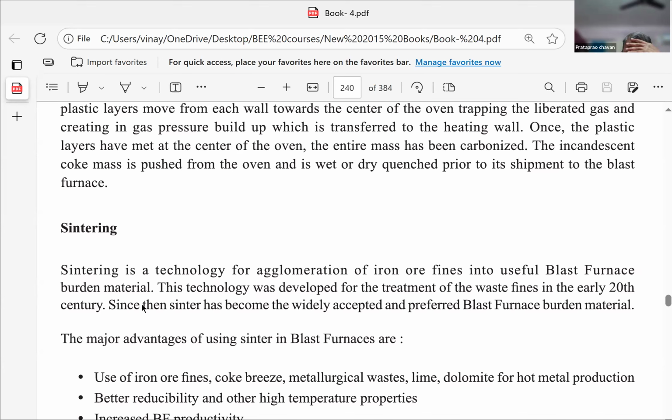So when you are feeding the furnace, solid pieces of 2 inch, 4 inch can directly be fed. If it is more than that, big stones like 10 inch, 12 inch, 15-inch size, they are to be broken. So a primary crusher is required.